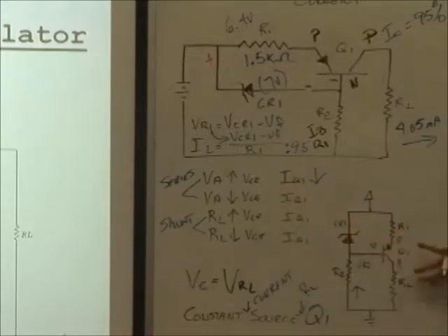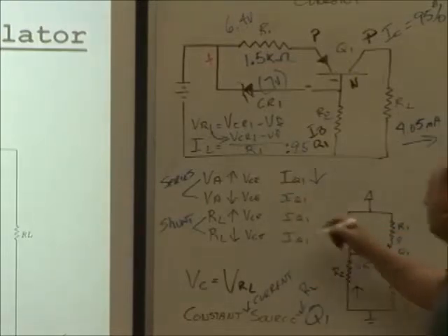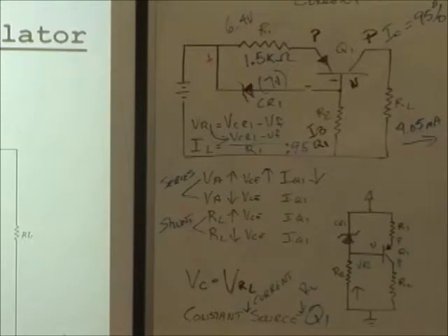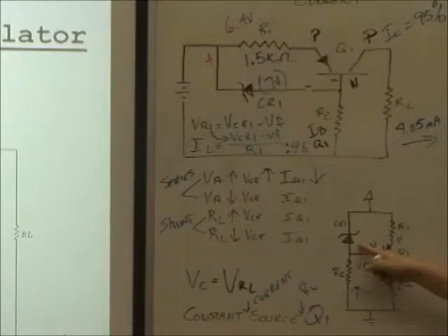Naturally, the VCE is going to do what? Increase. Because I don't want this current to do this, do I? No, sir. I want it to stay relatively constant, but if I increase the line, total current goes up, doesn't it? Yes, sir. So the circuit automatically senses that, and based on how it's configured with this Zener diode here, because it's keeping this top half of the circuit relatively constant, well, R2 is the guy in this circuit that, for the line side at least, increases or decreases its potential across the base.